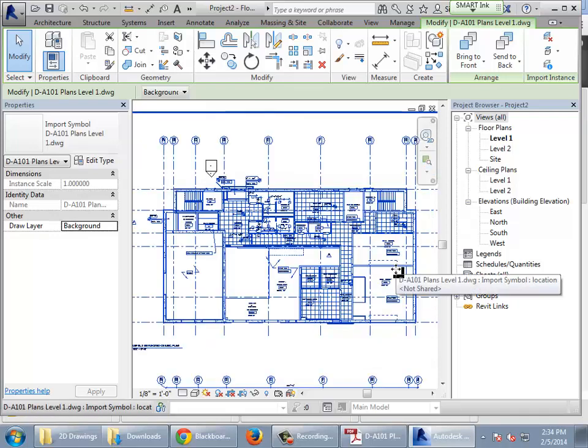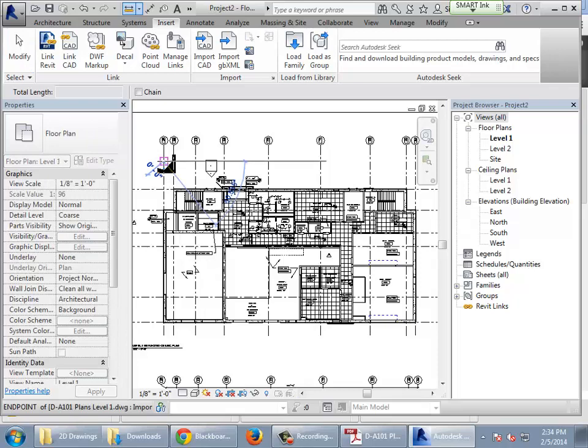So we should do the same sort of thing now. We should be able to measure really from what A is to J. And the nice thing about DWGs is you don't even have to use the little measuring stick, but it'll work. Again, it's 89. It's an interesting measurement right now. So again, it's not quite to scale. Our drawing right now, you'll see, is at 8th scale. When it brought it in, it's at some other scale. I'm not sure if it's 3/16 or some odd scale.